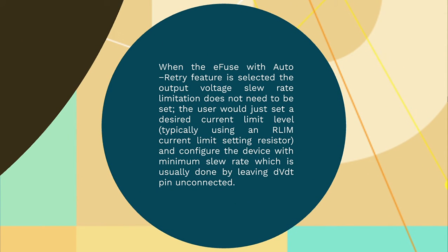Step 2. When the eFuse with auto-retry feature is selected, the output voltage slew rate limitation does not need to be set. The user will just set a desired current limit level and configure the device with minimum slew rate, which usually means leaving the dVdT pin unconnected.